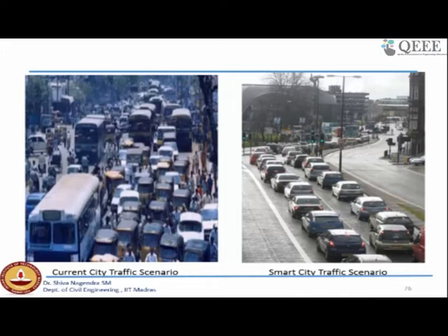Now I wanted to summarize my whole discussion from yesterday's session and today's session. You can use emissions control at the source itself. Maybe you can use a catalytic converter. Engine modification is one such thing. Now more efficient engines are coming up, and hence the emissions are also reducing. That's why your Euro norms or Bharat Stage norms look at the kind of technology that is available. That is why it is a long-term strategy.